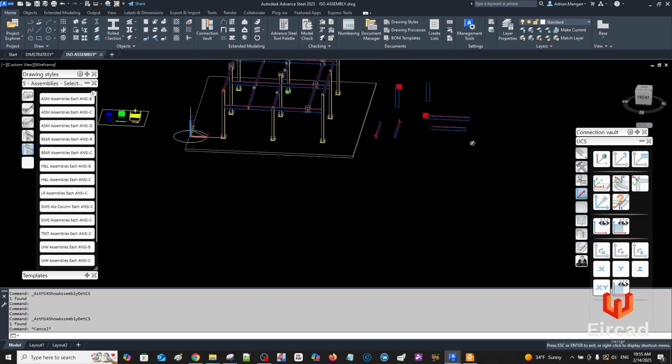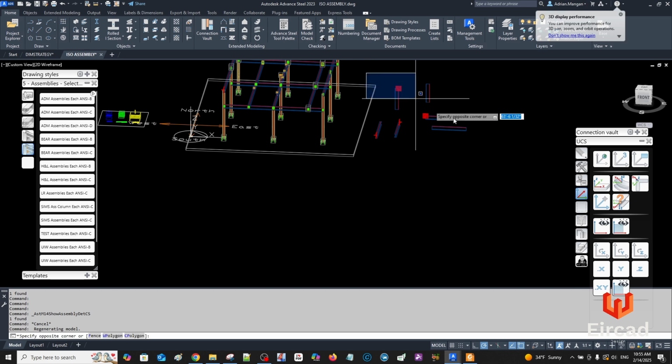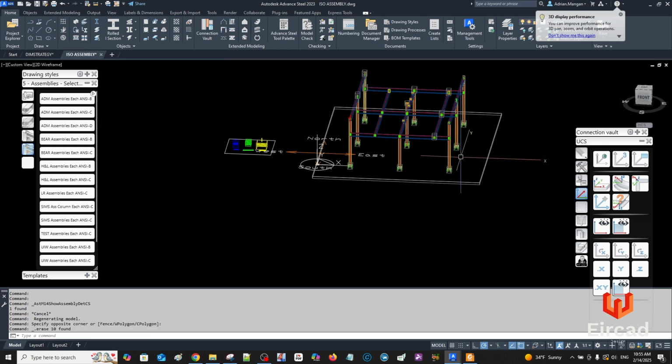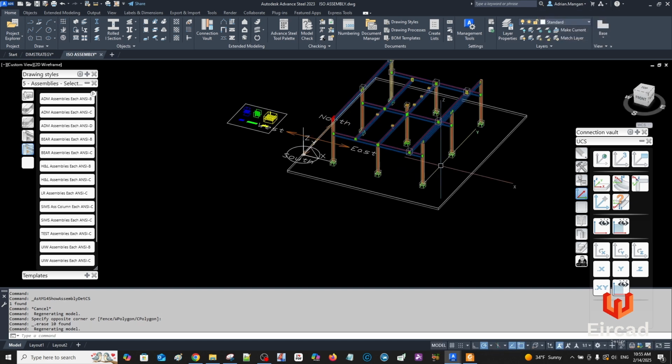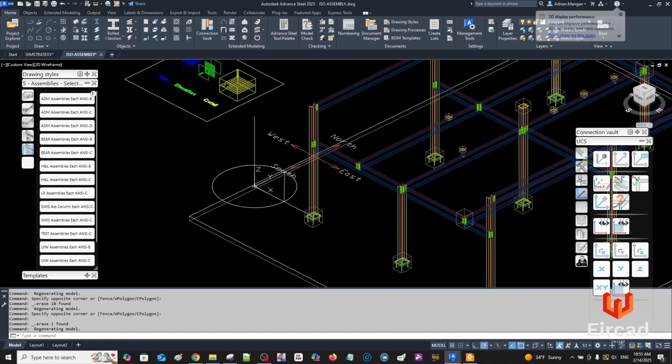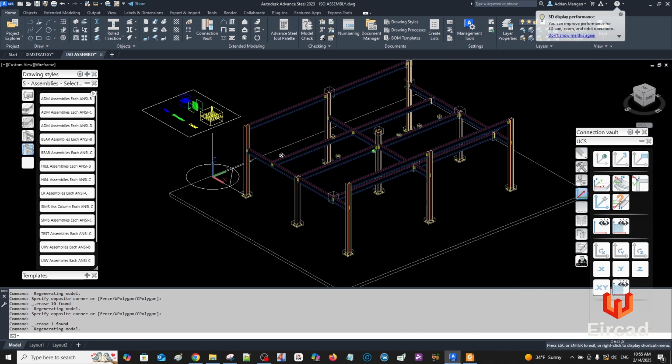So that'll show you what way your beams were drawn. If you're not sure, I would say just try to always model from the bottom up and the left to the right. Even now, probably just good to keep it accurate.